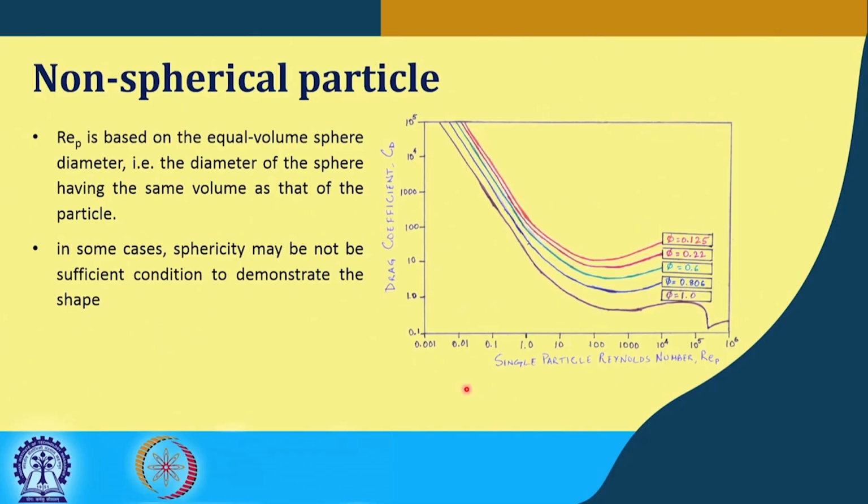Somehow the numerator and the denominator match, or the overall value matches 0.8. Then it is not a cube, but if by that value you determine it as a cube and calculate the drag force or the surface area exposed, your design calculation may be wrong. So the identification of the shape of the object is important, but in its absence, in case of bulk amount, we typically consider the sphericity, a factor which quantifies the deviation from the spherical shape.